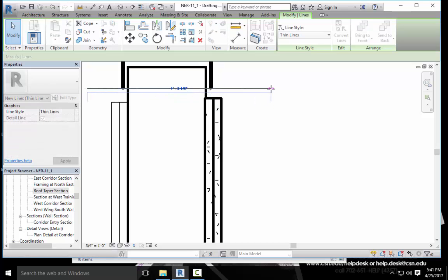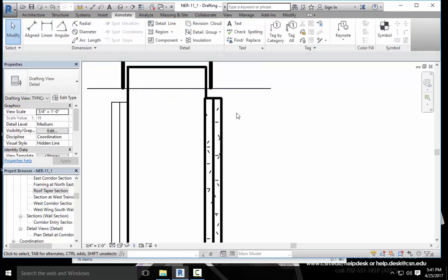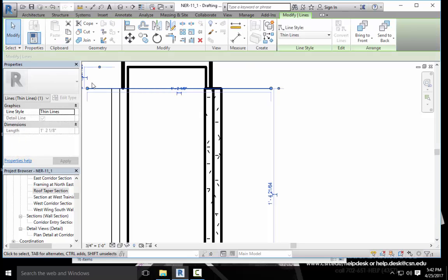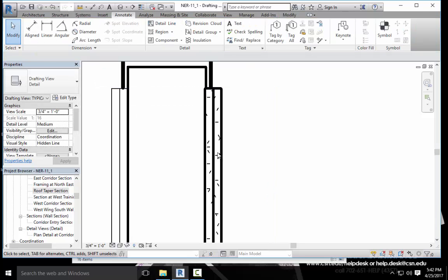And the reason I say that is it's all there, right? It's all together. I'm just using the align command right now to align these things. Then I'm just going to delete that line. This already has a hatch pattern on it. It has all those things. Now it needs some line weight work.